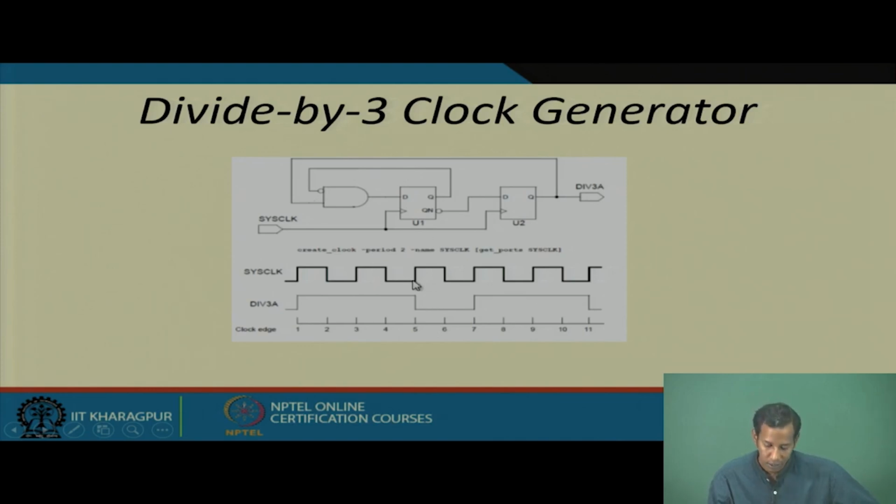So, whenever it counts this 2 over here, at that time it will make the sequence 0, then again you count 0, 1, 2, and then again make it 0. Or instead of that, you can make one FSM kind of thing. So, there will be this 0, 1, 2. If you develop from that excitation table you draw, and then come down to the logic of that, it will become the corresponding circuit.